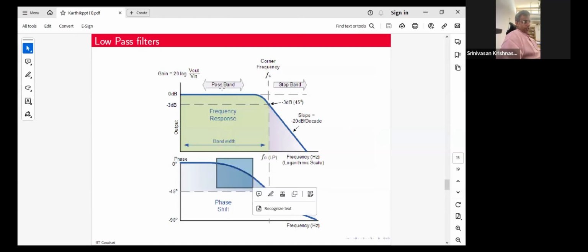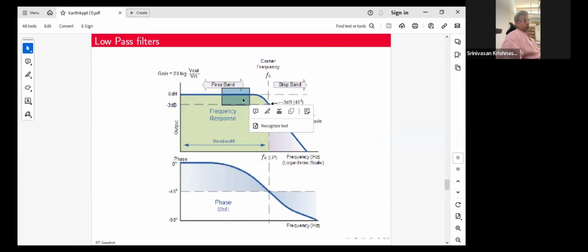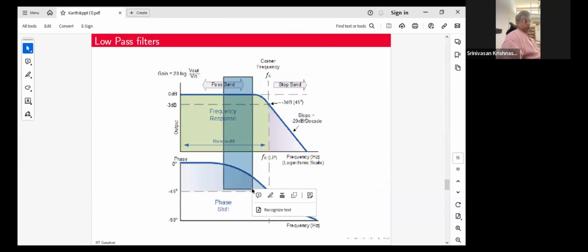Which means that if you look at this particular band of your frequency response, your amplitude response is nearly flat, which means that the magnification that different frequencies have is not very different, but your phase delays begin to change.